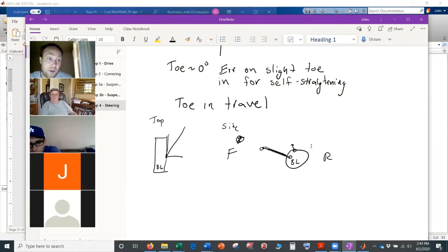We talked a little bit last time about how you can have jacking on the side view, which is good. It's also nice because your tire moves in this direction, so if it hits a bump, it kind of comes back. This top view packaging is also nice because instead of having equal arms, now you need a mounting point way back here. So you need your frame to extend way back if you want to get the wheelbase. You can make your frame smaller and connect here if you can get that point.